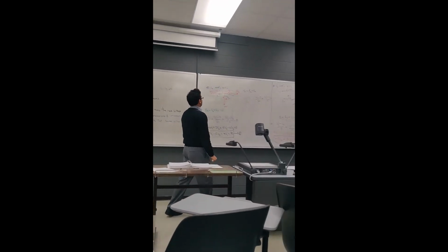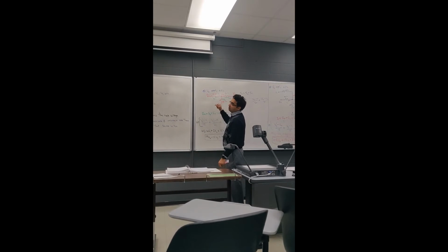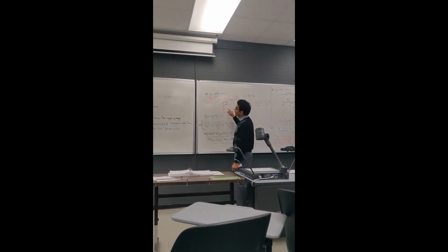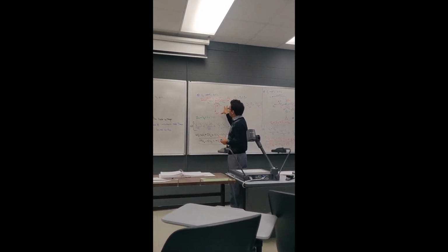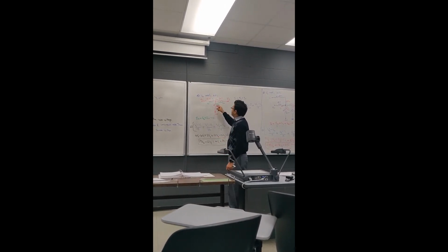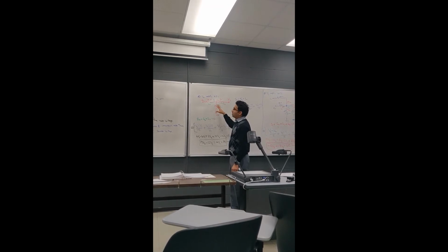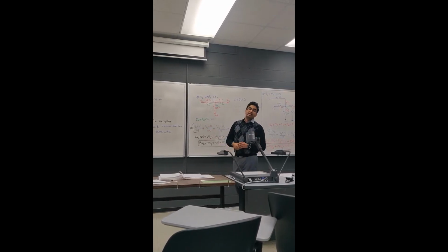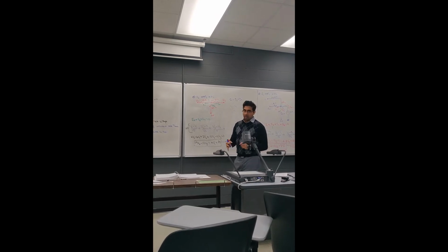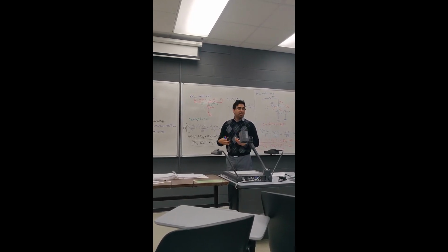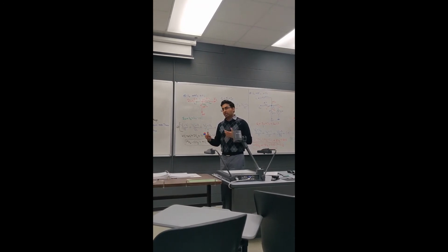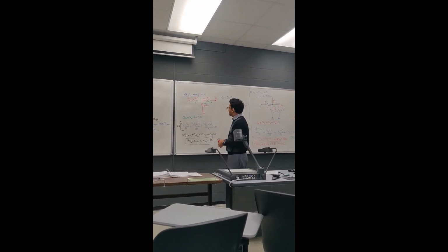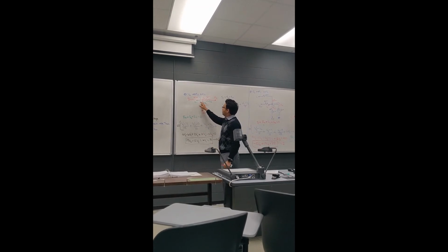At node 2, for sure, there is no voltage source between V2 and the reference, so we need to apply KCL there. So here at V2, I'm trying to apply KCL. I have IA, IB, IC, all currents going out. KCL is nothing but Kirchhoff's current law. So currents coming in must be equal to currents going out, or all the currents going in or going out must sum to 0. So I'm choosing all the currents going out: IA plus IB plus IC equals 0.